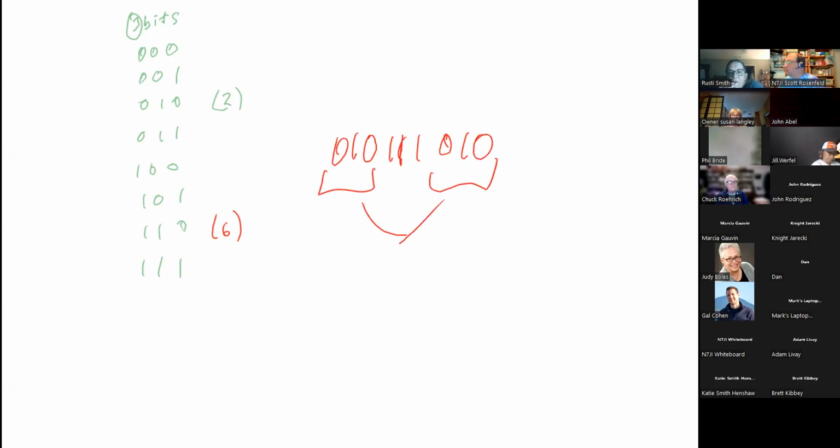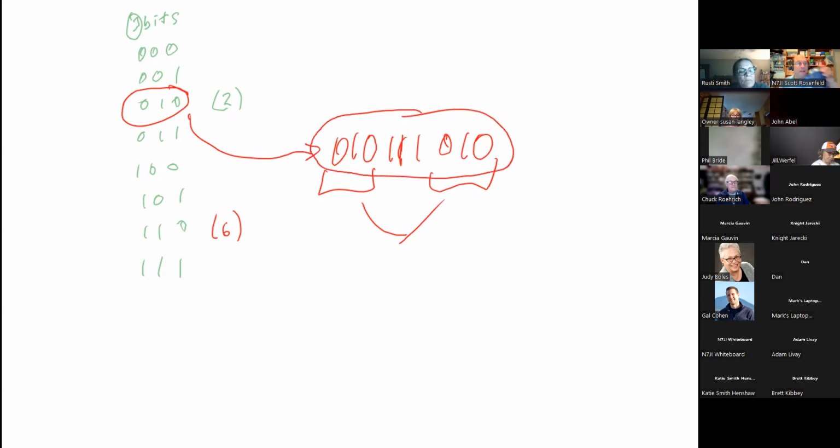Now, what do you notice about what you sent originally and how much time it took to do it? The more you have to duplicate, the more time it would take. Which means that it slows down your data. Okay. Exactly right. So digital modes are great to have, and sometimes the amount of error correction and detection that you throw in there determines how much you slow them down. Sometimes it might be worth it, sometimes it might not.